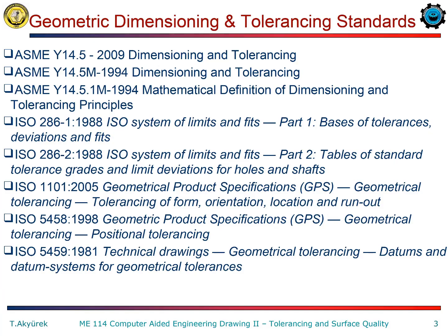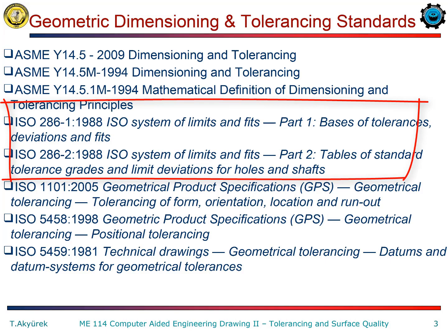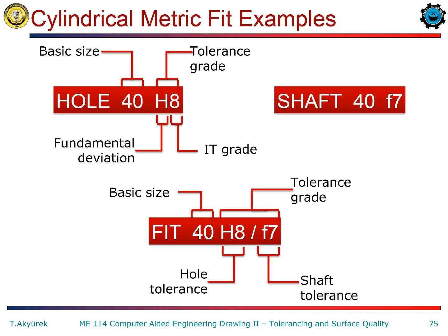We determine the tolerances by using international standards according to the functionality of the parts. In Turkey we use ISO 286-1 and 2. We show the tolerances of a dimension in different ways in technical drawings, with plus and minus signs or with the representations which are defined in the international standards.